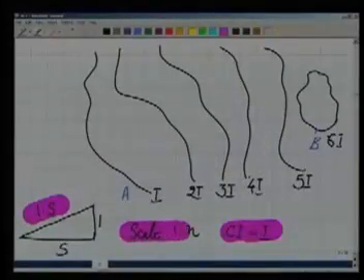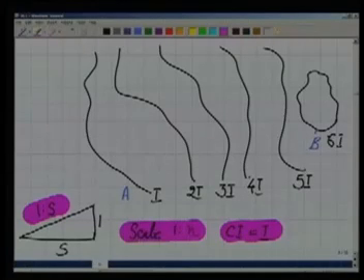So this is the slope. We want to maintain this slope of 1:s everywhere on this contour map. For our corridor, whether it is a pipeline, railway or road, we need that kind of contour gradient. Now how to do that? Let us say the scale of the contour map is 1:s.